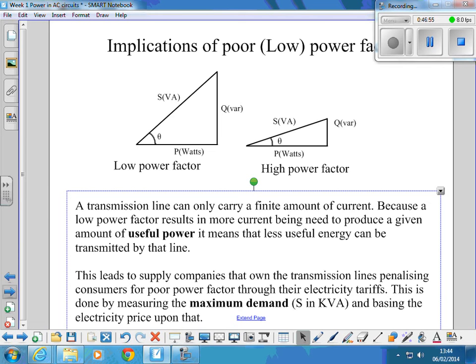It was a meter that had a needle on it in them days. You know, the types of things where the needle pushes a maximum marker up beyond where it was before, so when it falls back, the marker still shows the maximum. It's probably electronic now, but they'd have a meter that indicated what your maximum demand was in that month. I think you used to take a reading of demand every so often and then record what the highest was. And they'll then make a monthly charge based on that highest demand.